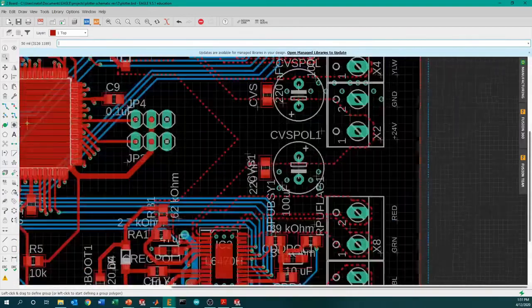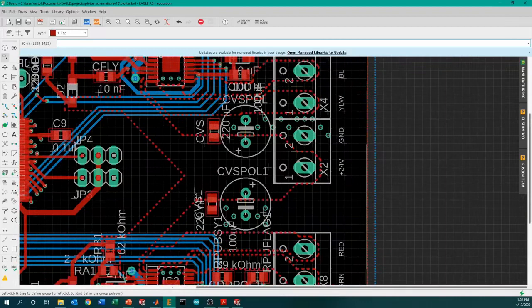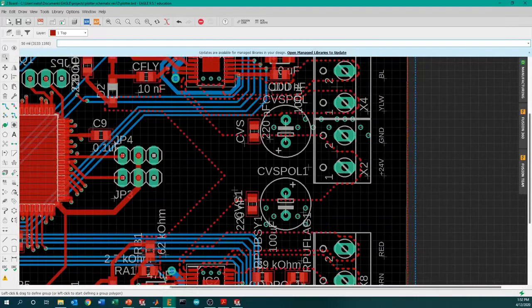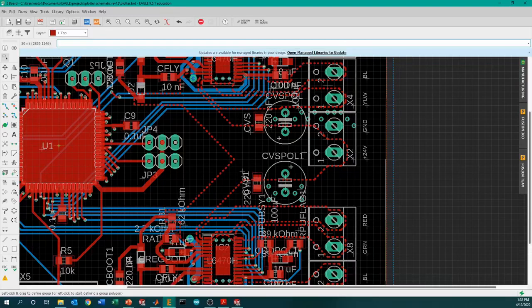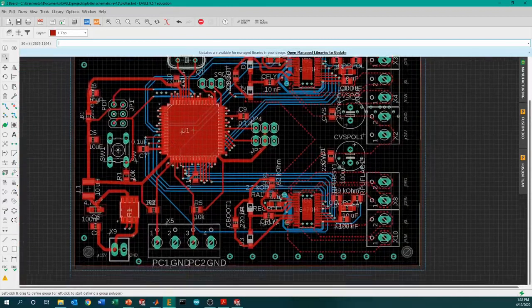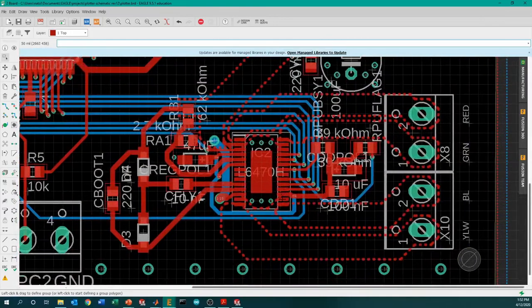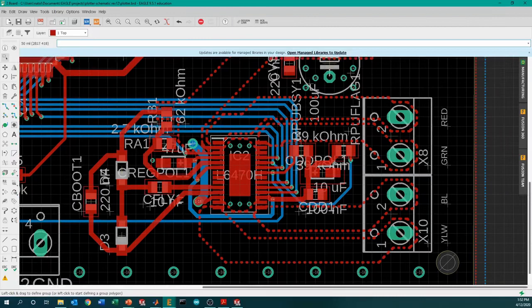Basically, we have a single dedicated terminal block that brings in our 24-volt power, then the large polarized and small non-polarized capacitors that we have across that. And then finally into our two individual motor driver boards themselves. And we also, as you can see, use four polygons to connect them to the four terminals per block that would attach to the poles of the motors.